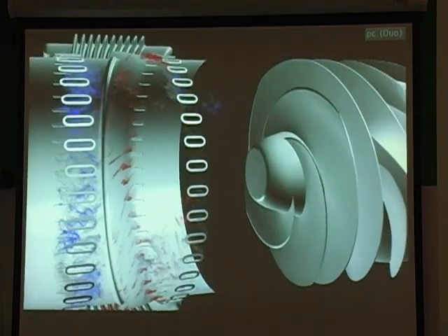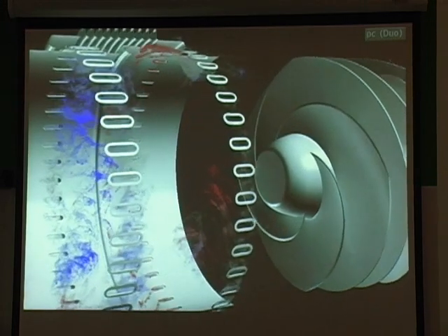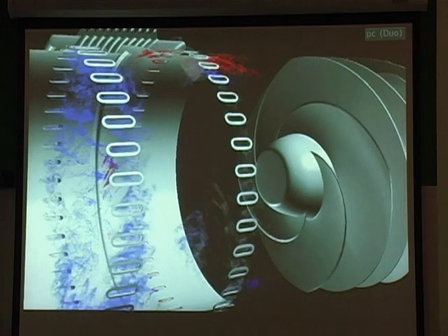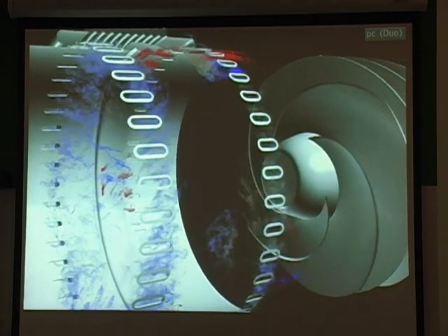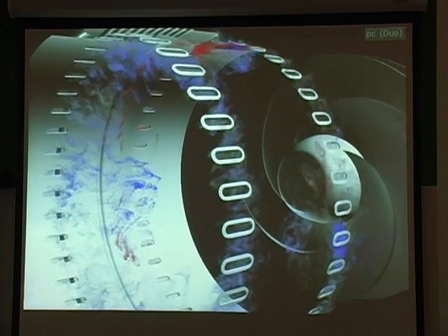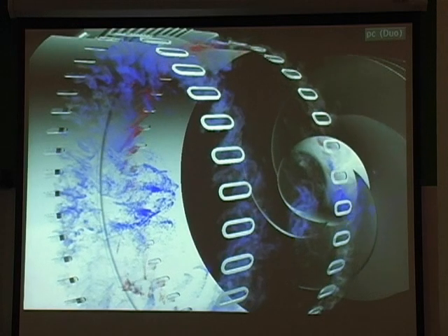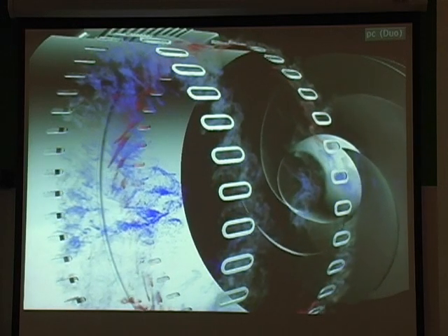These are actually ports that are put into this flow liner to retrieve welding debris after the joint is formed. So they weren't initially designed with flow in mind. But in use, the liquid hydrogen actually flows in both directions, it turns out, through these holes.